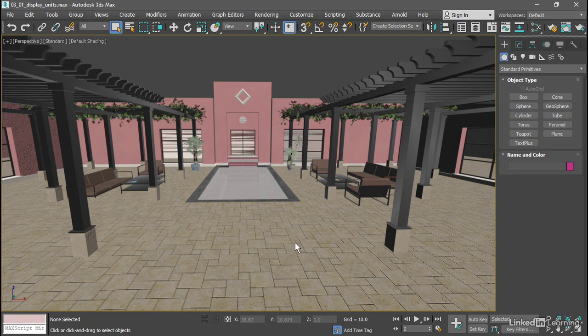The size of the world and the size of objects is super important, especially when you get to physical materials and lighting. You can't expect good results if the objects are not scaled properly. It's strongly advised that you model everything to unity scale or 1-to-1 scale. In other words, the object in the 3D scene is measured the same as it would be in the real world. If you have a scene open and you don't know the scale of objects, there's an old trick to find that out by just basically building a box.